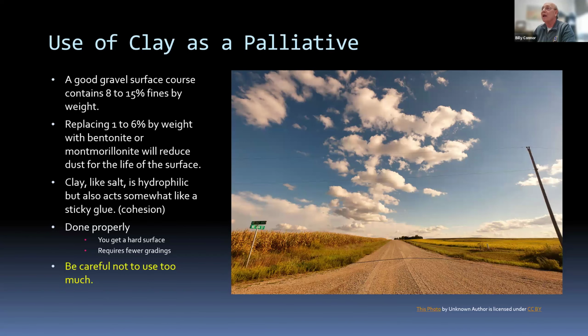Let's talk a little bit about clay. Clay is a very good palliative, as it turns out. We've used it a number of times when I was working for DOT, and DOT is going back to that on the Hall Road with some experiments they're doing, I think, this summer. Remember that we're looking for gravel surface course to have about 8 to 15% fines by weight.